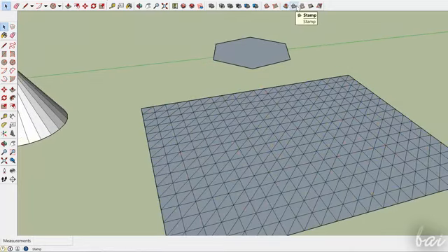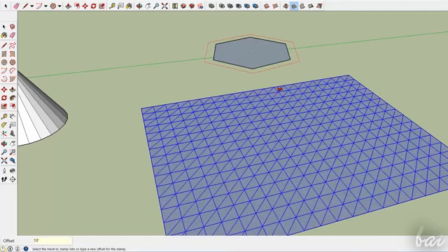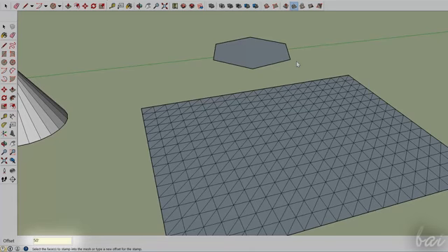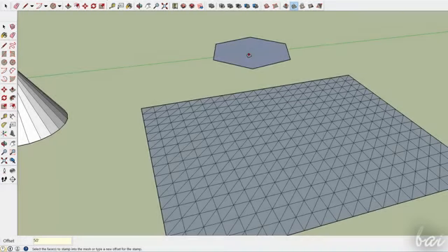The Stamp tool is used to create faster mesh objects with complex shapes. First of all, you need to select a plane face or a solid group that lays above or below the part of the mesh you want to modify. Define then the offset by typing with your keyboard and confirm with the Enter key. This offset is represented by a red shape distant as much as you defined.